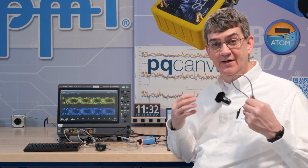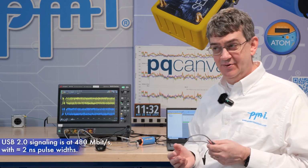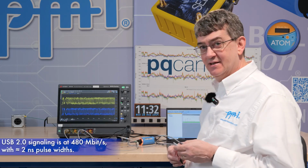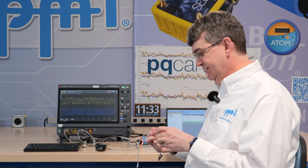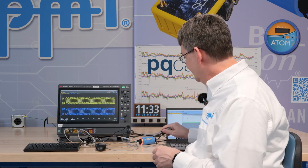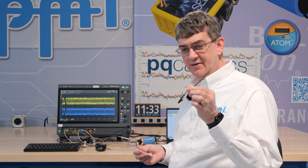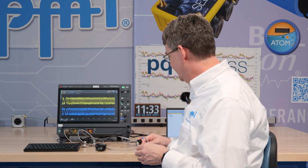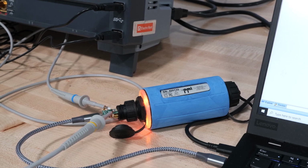Because it's 480 megabits per second, that's a very fast pulse width. That's a 2 nanosecond pulse time. So we need some specialized equipment to look at these signals. We're going to be testing the USB-C adapter and USB cable we supply with the Bolt. And to do this, we need a high-speed oscilloscope with some special probing. The normal scope probe ground lead and scope probe tip have too much inductance to get accurate measurements. So we soldered scope probes directly onto the circuit board interface of this USB-C connector.